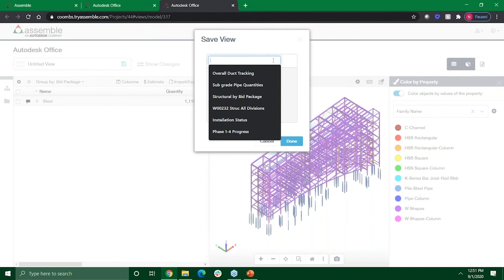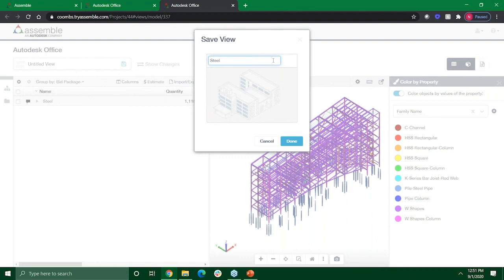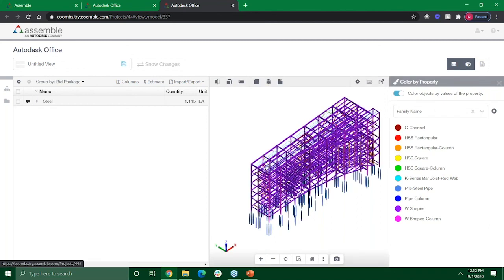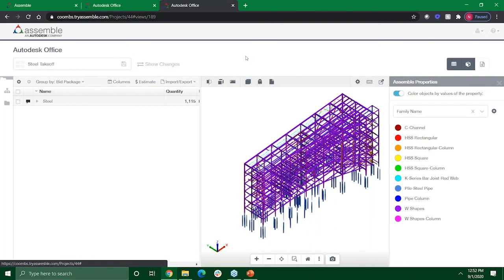The idea here is I'm not going to run through field workflows because I don't need to. The only thing that you won't have seen that's required in the field workflow is the iPad. And that's the same concept as we have here, where we have the ability to add information as we need it. We have the ability to save it out as an intelligent view. And then if you want to colorize this based on your statuses, you use that parameter of status. You want to organize this by what's installed and what's not, you use that same parameter. We can then take this to Power BI. We can then take this to all sorts of different places.